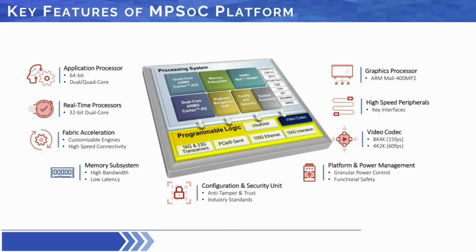And these adaptive SoCs complement the decade-long availability of soft-core CPUs and other soft IP for building systems on FPGA-based solutions. And with this extended memory subsystem, there's a provision for increased bandwidth and added support for DDR4 and other memory technologies. The MPSoC includes an all-new graphics system for 2D and 3D rendering that you would commonly need for your GUI and displays, which we will be touching upon in the next few slides.